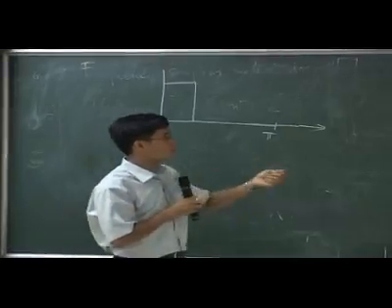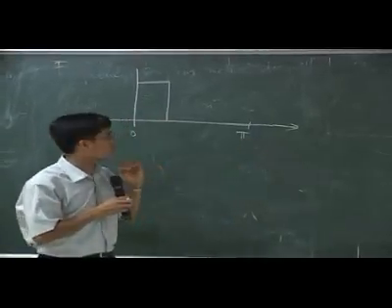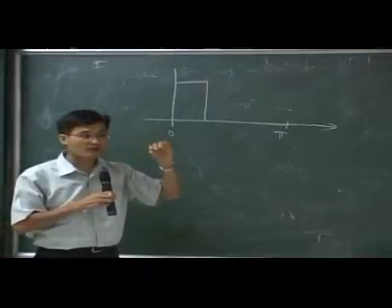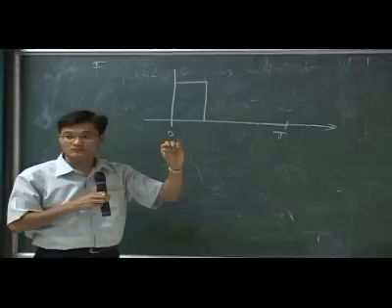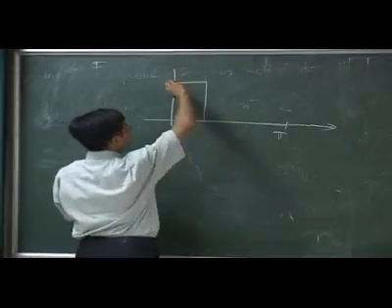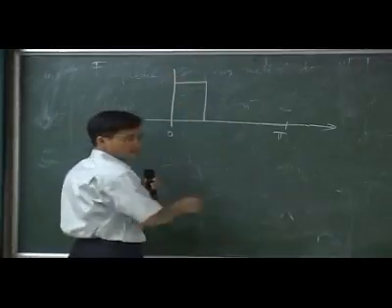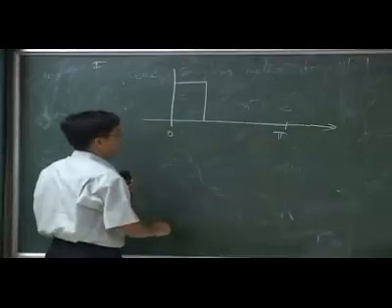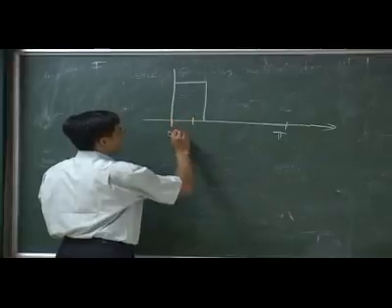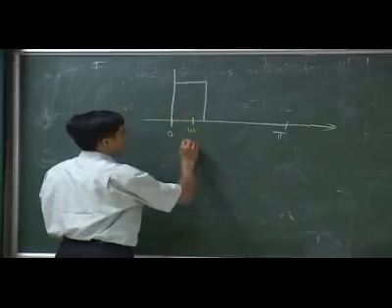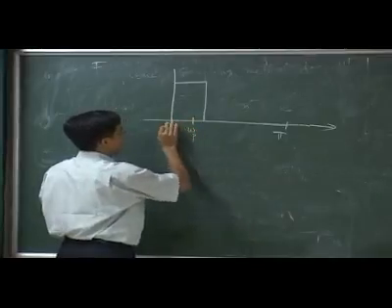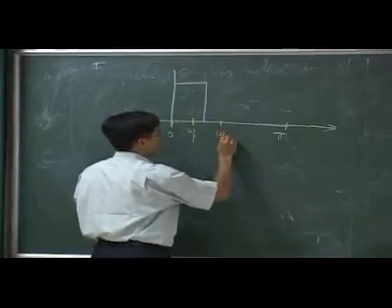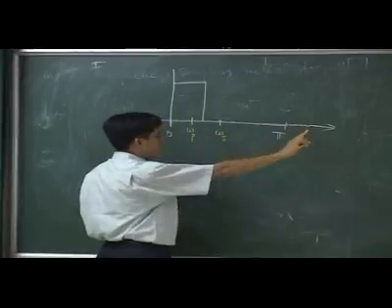And now instead of enforcing only a certain point, I want to enforce anywhere, but now with some tolerance. I allow them to wiggle, but I want to control that wiggle. So the thing here, for example, I have this filter, and I would say that, okay, here's my ideal filter, but now I'm saying, actually, I really want from 0 to omega P, I really want the signal go through. From omega s to pi, I want it going to be stopped.